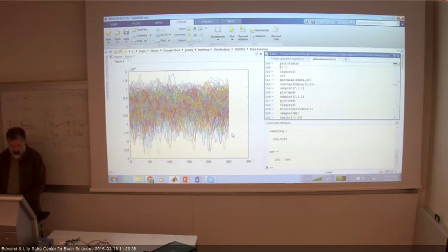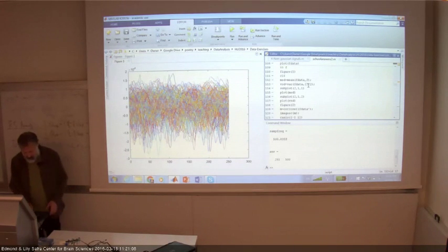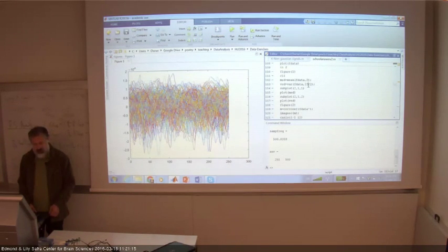And I have 251 points on each trial now. Yes. To calculate the correlation matrix and get something that's 250 by 250 instead of 12,020 by 12,020. Memory, runtime, all kinds of things like that. I could also not do it, but there was no point. And in a way, it's good practice. If you work with slow signals, there's no point in having them sampled at very, very high rates. So maybe you don't want to go to the Nyquist frequency, but you also don't want to work at 200 times the Nyquist frequency. There's no point.